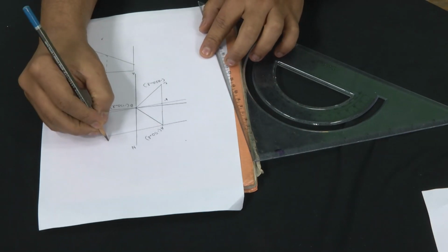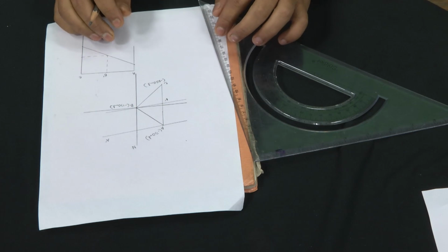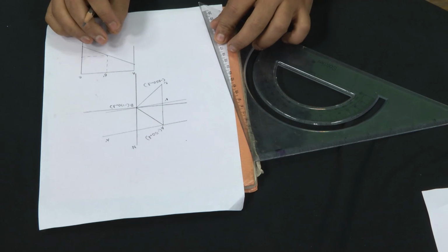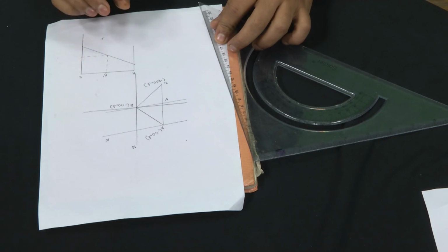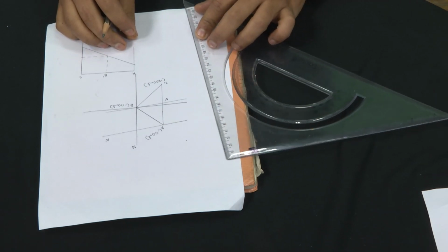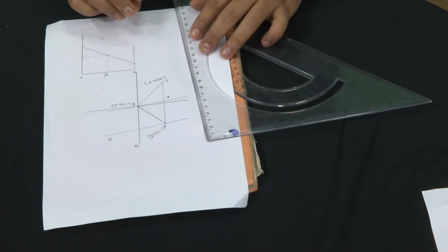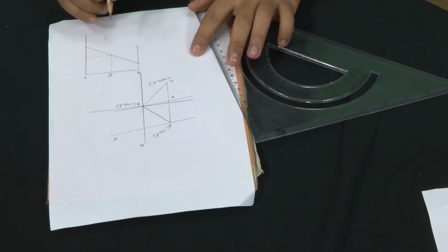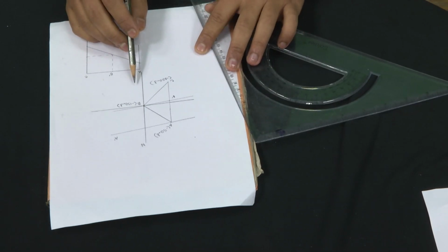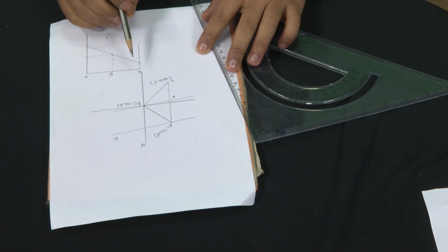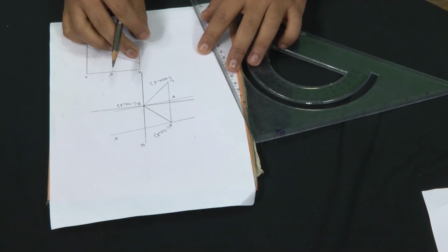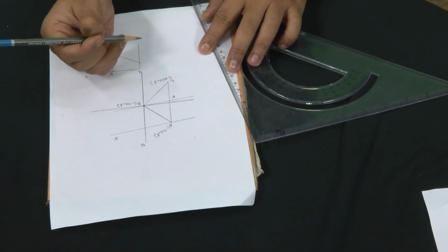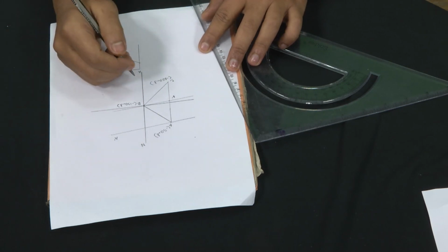So, I name it A dash. So, now basically what we have is that we have the strike lines of two depths of the ore body, one A dash, which is the strike line of the ore body corresponding to minus 50 meters depth, and another is B dash, which is the strike line of the ore body corresponding to minus 130 meter depths. Clearly minus 130 meter is below minus 50 meter. So, the bed is dipping towards this direction.